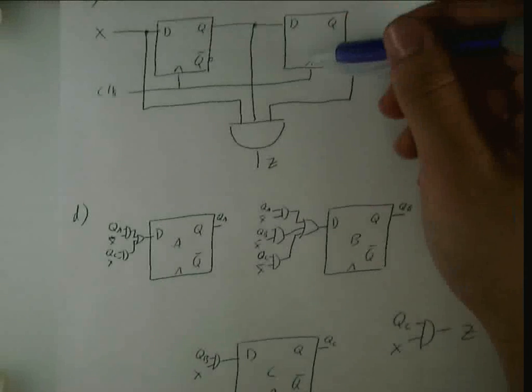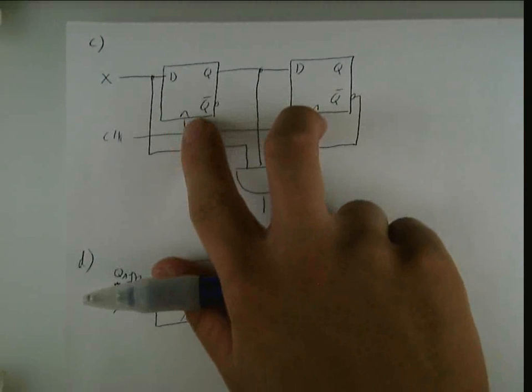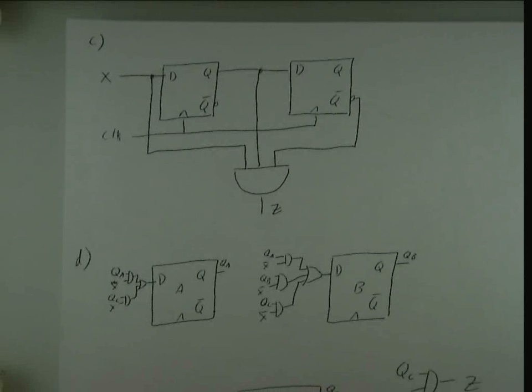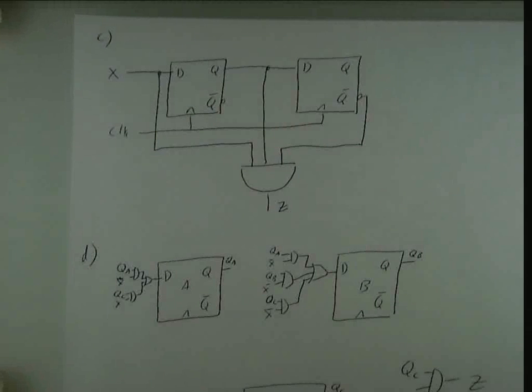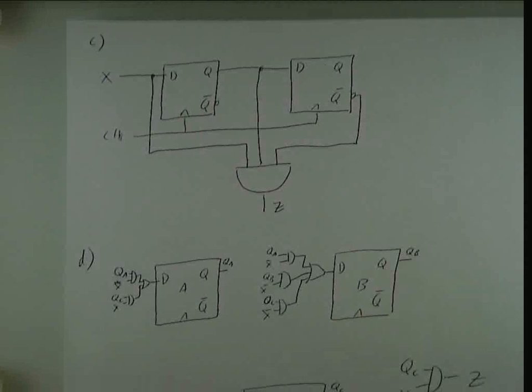And same thing with the window on the input. This is just inputting a shift register, and so its states are encoded again differently than the way I encoded them in the original problem statement. And so if I encoded the states better, I could have actually come up with the window on the input design with the correct encoding. But the state definitions are different than in the actual state machine, and so the encodings are different, so therefore in one sense they are not equivalent, and so those are potentially 2 valid answers.